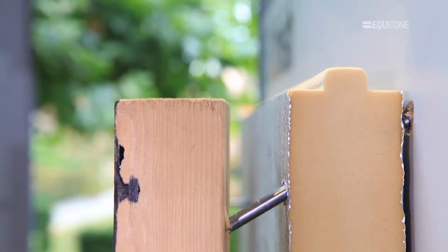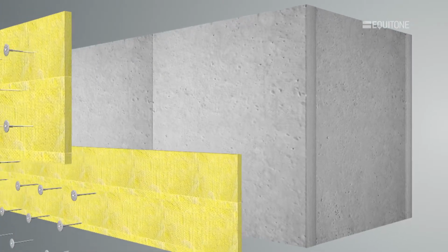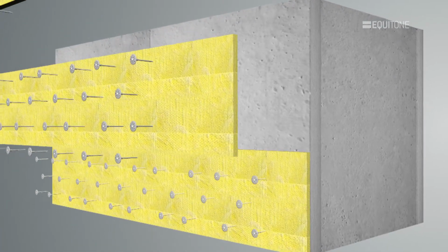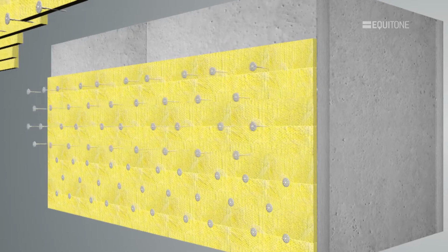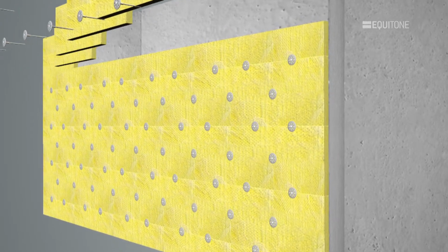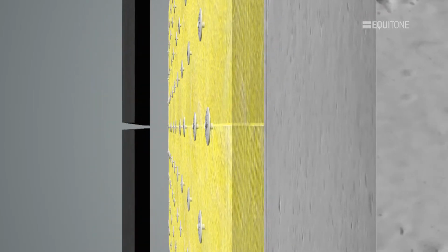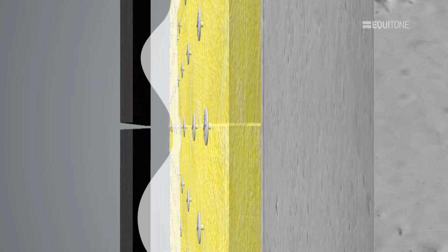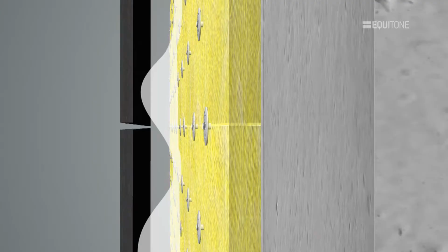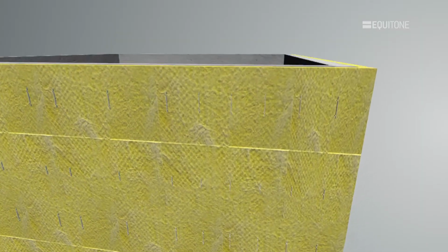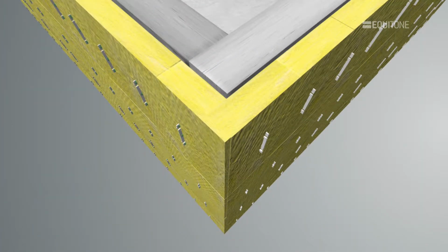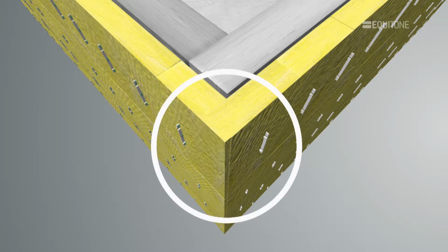To meet these criteria, a number of insulation suppliers have a board for ventilated facades. Whichever insulation board is chosen, they must all be securely fixed to the structure, which is normally with special fastenings. Over time, the insulation must not sag or bulge out to block the air cavity. It is important that the insulation has no gaps at its joints and fits tightly around the subconstruction to reduce heat loss.